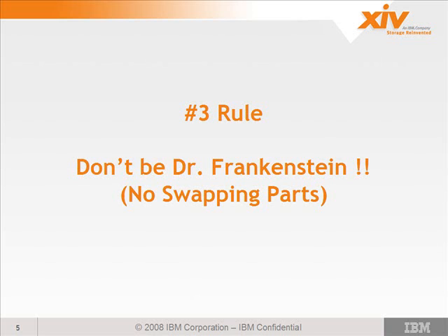You don't want to swap USB to serial cables. You say, oh, this one might not be working. Actually, the USB to serial on the UPSs are different than the USB to serial going to the other modules. So you plug in the wrong USB to serial cable on a UPS, and that UPS is going down. It goes down hard. I found that out because I was playing Dr. Frankenstein. I got my hand slapped too.